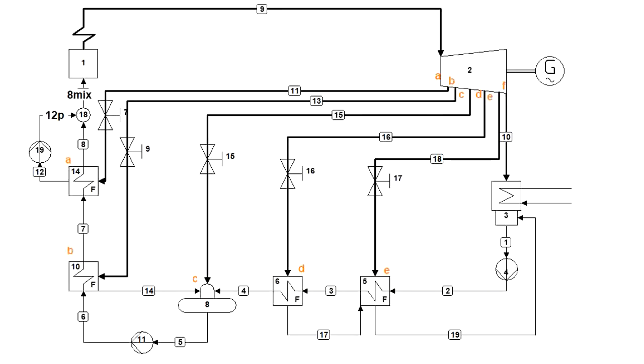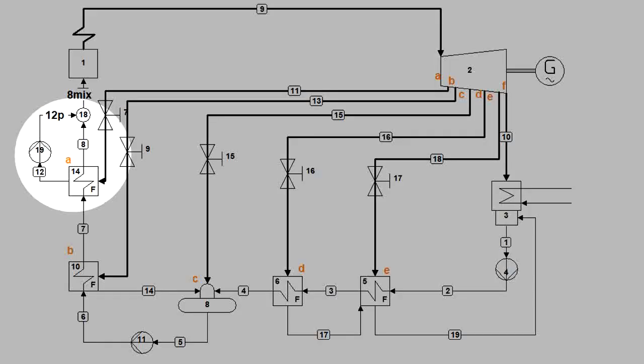In the previous problem, we cascaded all the condensate downstream into either the aerator or the condenser. In this problem, we will show an alternative option where, as you can see here, we don't need to cascade the condensate from the feedwater heater, but we can use a small pump to increase its pressure and mix it with the main feedwater.